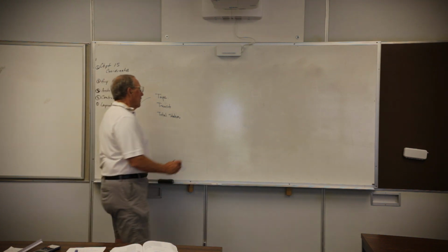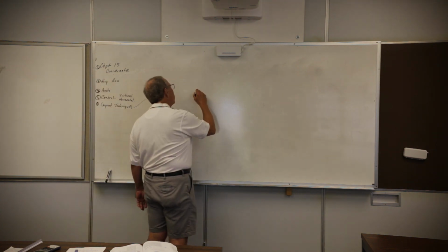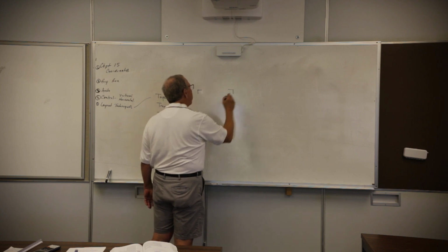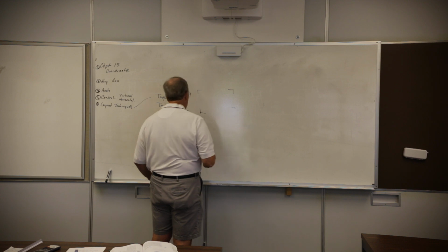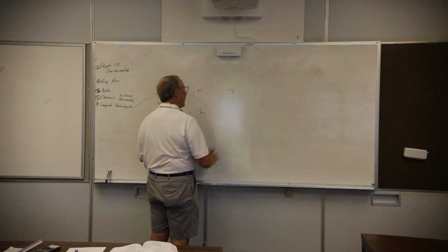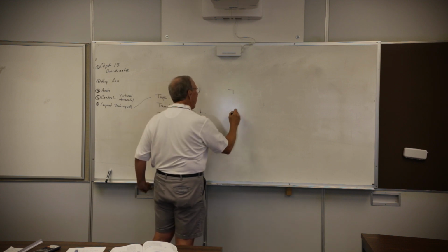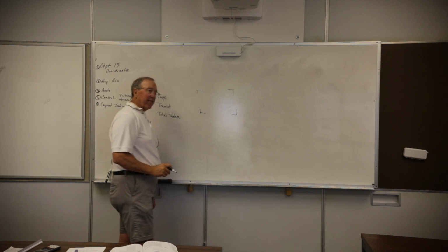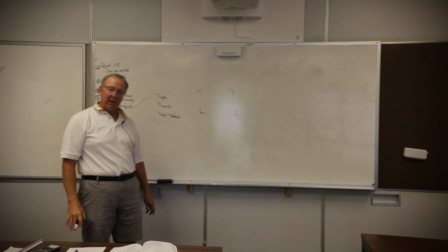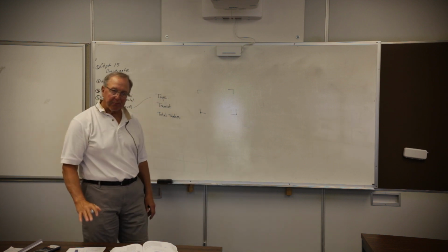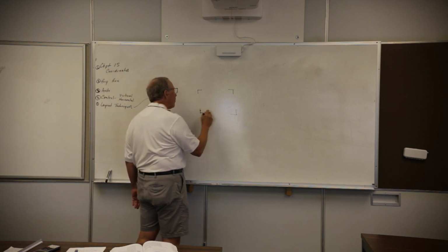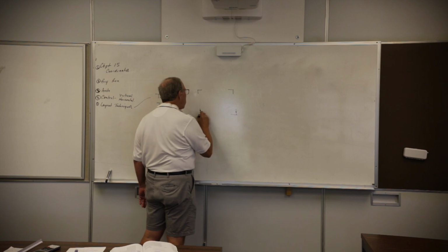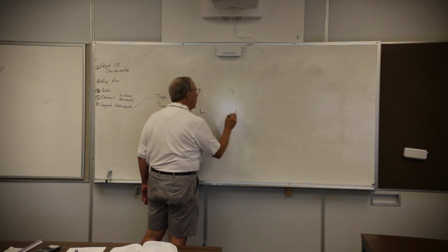A tape measure, I've seen people use batter boards to lay something out. Batter boards are just boards that stick up into the air at right angles. If I was in the field, I would look at them. It would be like little hurdles. And we put nails at the proper position in those horizontal boards.